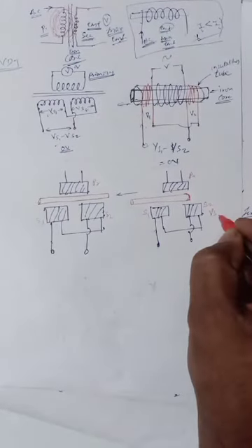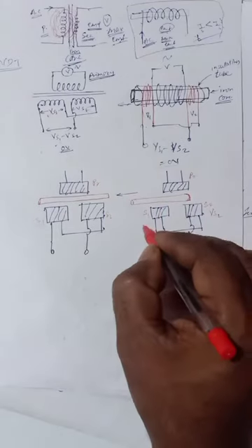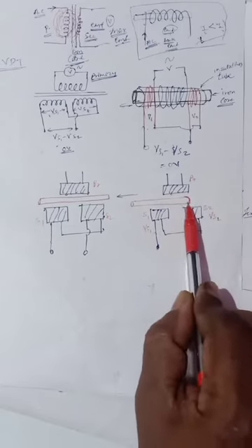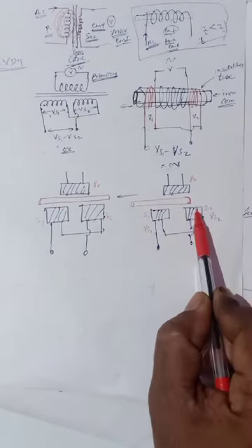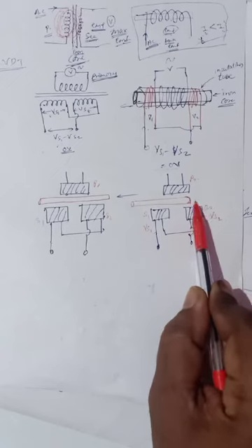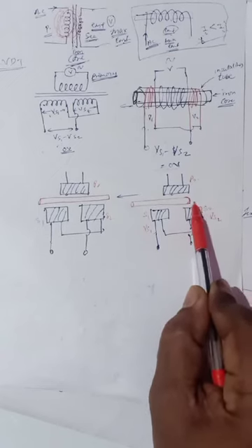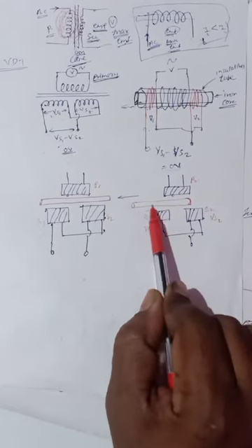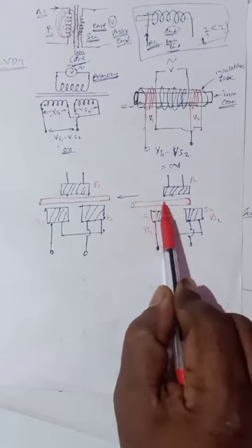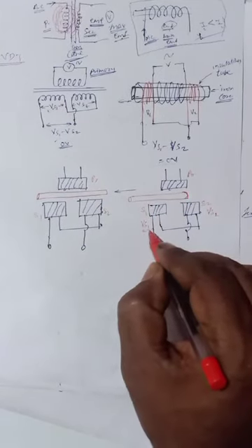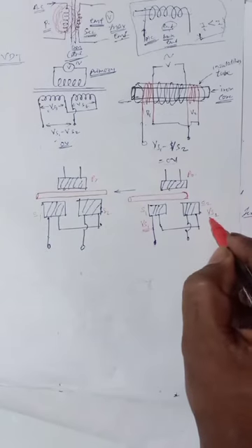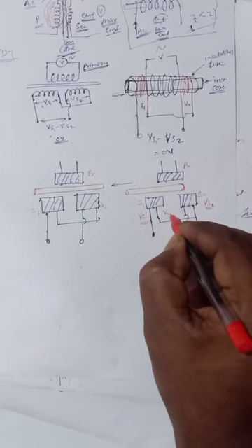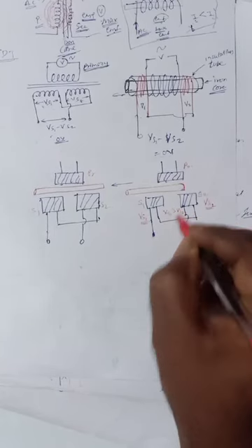Whatever voltage is developed is Vs2 here and Vs1 there. If the rod is moved from the left side, this coil is half iron core and half air core, and this coil is full iron core. If we compare the two voltages, Vs1 is greater than Vs2. Why?